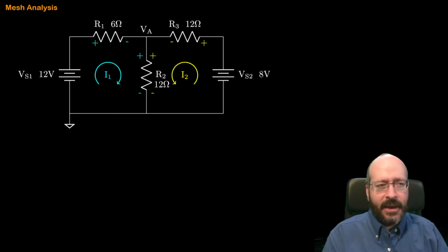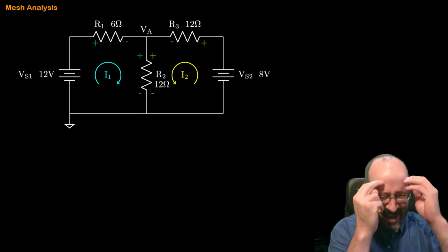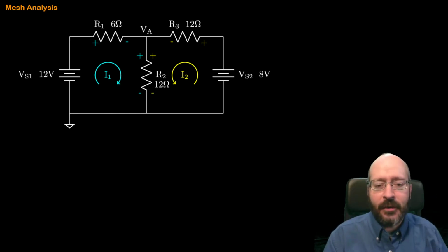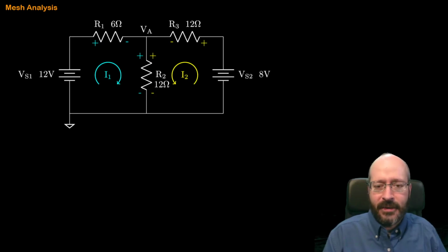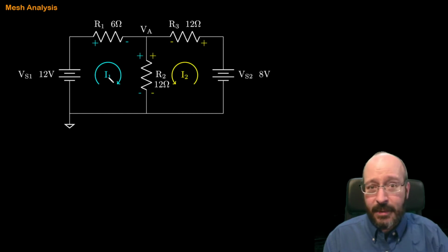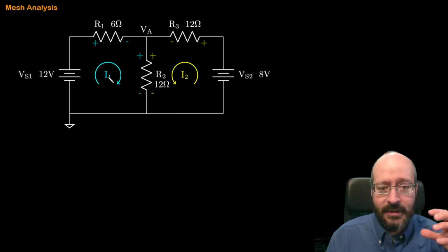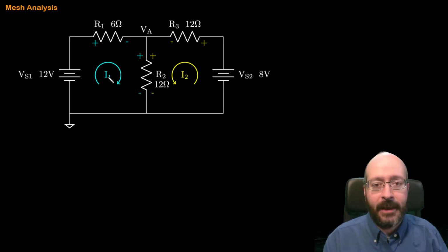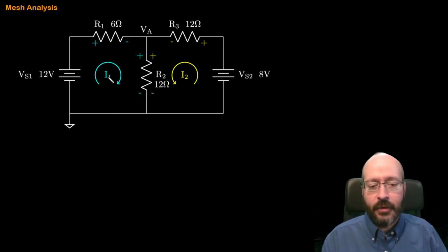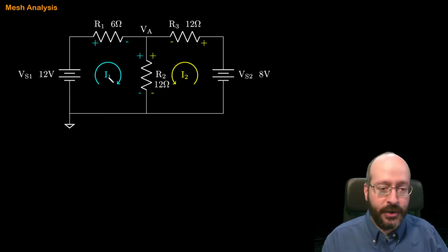That's fine, and they probably use the concept of R total, and I absolutely hate the concept of R total because, well, which supply are you going to lose? You can't do that with two supplies. Which one are you looking from at any given time? So those analysis methods are limited. With mesh analysis, piece of cake. You just treat it as another voltage, you include it in your KVL, and you're good to go.